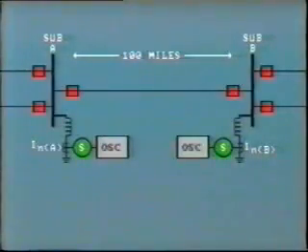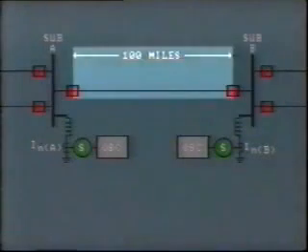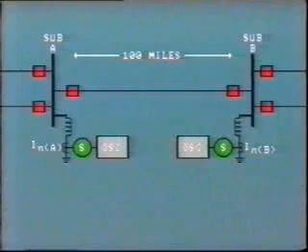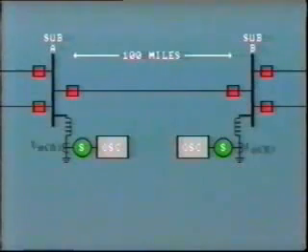Here's an example of how oscillograms, along with some computer simulations, can help pinpoint the location of trouble areas along a transmission line. The system one-line diagram shows 2 substations, A and B, separated by 100 miles of line. Both stations are equipped with oscillographs that monitor transformer neutral currents INA and INB.